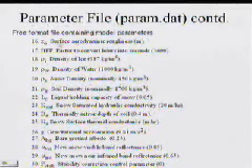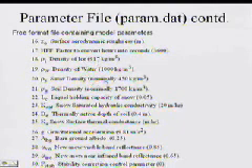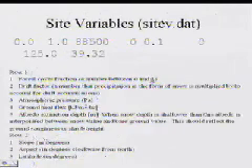Then the surface aerodynamic roughness, you may want to change this. This was one of the parameters we calibrated. The factor to convert hours into seconds, that's pretty much set. Density of ice, density of water. Snow density, this you may want to adjust. Soil density, again, there's a site-dependent condition. The liquid holding capacity of the snow. The saturated conductivity, this was the value that we calibrated, but it was within the range that you get in the literature. So and so on. So you can see these are the parameters that are in that param.dat file.